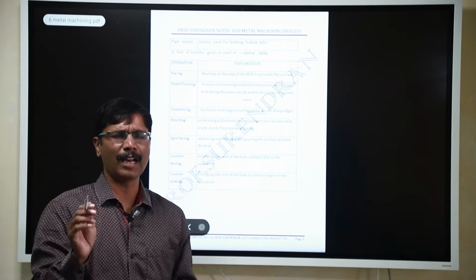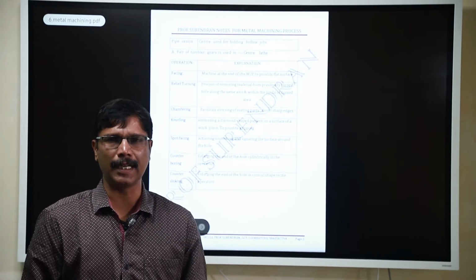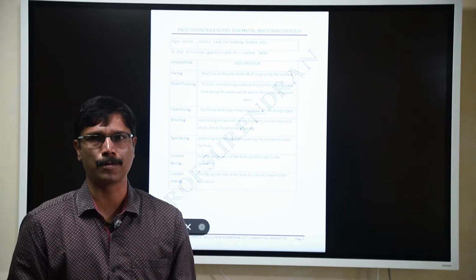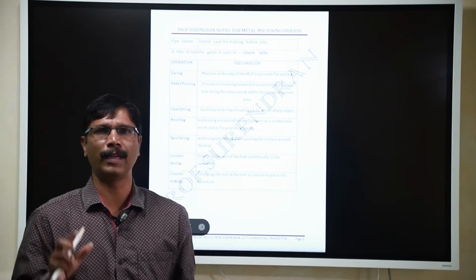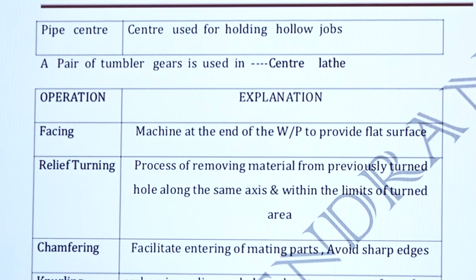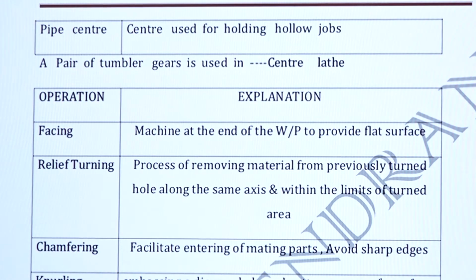So next we are having pipe center. What is that pipe center? It is used to hold the hollow jobs. So when the job itself is hollow, we have to hold the hollow job with the help of pipe center. Next we are having the different operations.